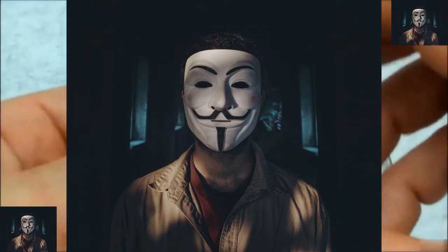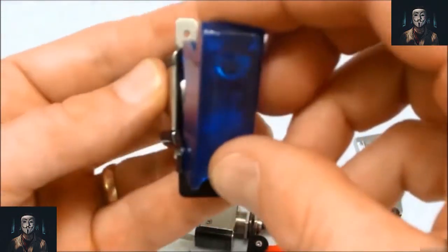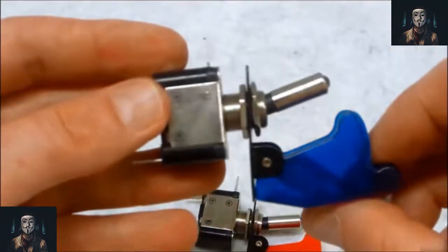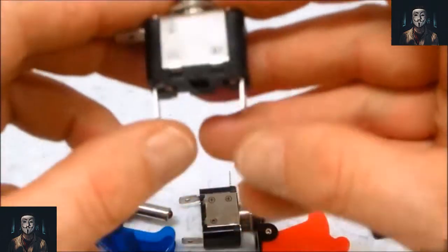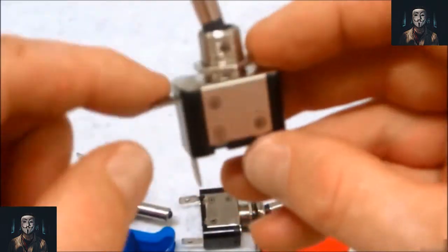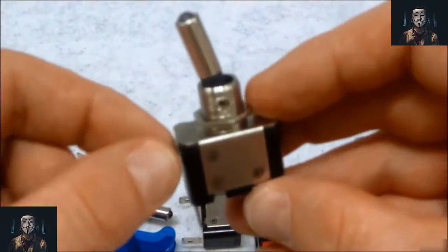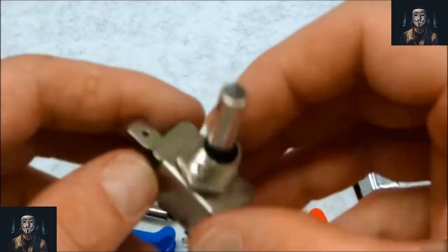The simplest type of switch is the single pole, single throw switch. This switch controls the on-off operation of a single circuit. The most common type of SPST switch design is the hinged pole. The pole acts as the contact and changes position as directed to open or close the circuit.